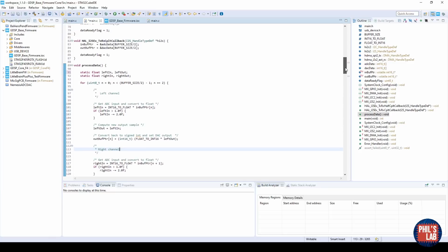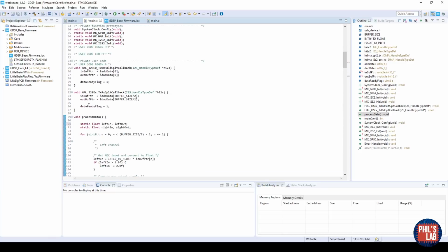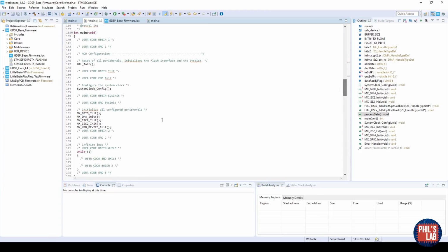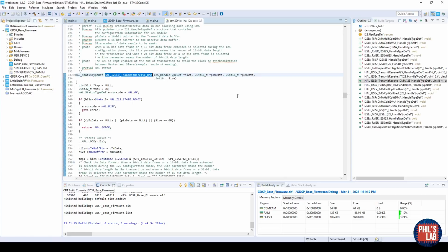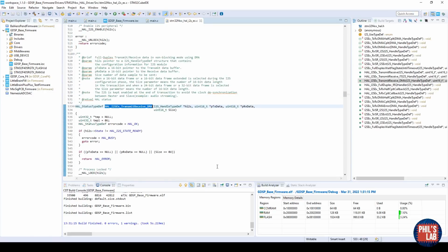The last step is that we actually have to start these I2S DMA streams. And the way we do that is in int main after all of this configuration. So somewhere here, before we go into our main while loop, we need to start our DMA streams. So I've already written the function out for us here. And in Cube-IDE, if you control click, you can go through to that function prototype, or the function definition rather. And you can see all of the parameters and so on. So let's go through that one by one.